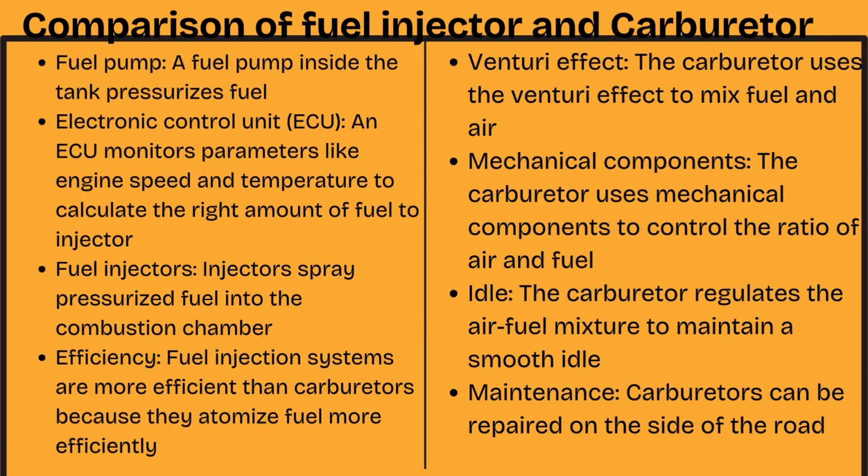Comparison of fuel injector and carburetor. Fuel pump. A fuel pump inside the tank pressurizes fuel. Electronic control unit, ECU. An ECU monitors parameters like engine speed and temperature to calculate the right amount of fuel to the injector. Fuel injectors. Injectors spray pressurized fuel into the combustion chamber.